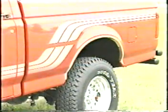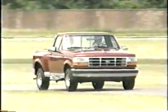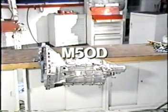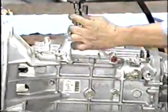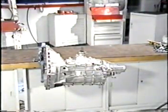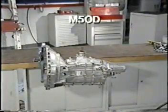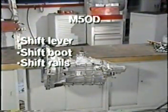Assume we're dealing with a rear-wheel drive 5-speed transmission, such as the M50D used in F-Series trucks. Problems with the shifting components are a likely source of these shift concerns, but not the only possible source. You should check the shift mechanisms first, however, because they'll usually be easier to get to and repair. The shift mechanisms for this M50D 5-speed, for example, include the shift lever, the shift boot, the shift rails, and the shift forks.